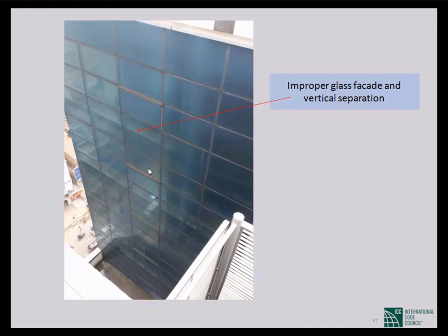Actually, there is zero separation. If there is a fire in the lower floor, the fire will move through this gap with zero vertical separation. There should be no building with zero fire separation. At least 2 or 3 hours fire separation. You have already seen this from the table, which I just finished a few minutes ago.